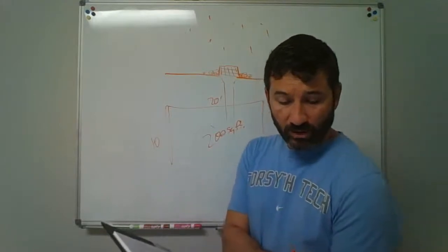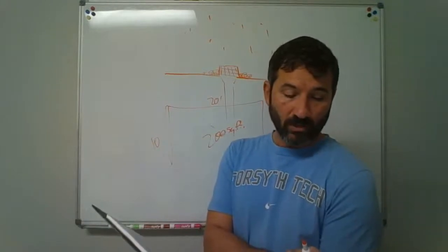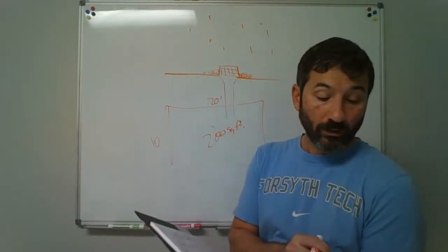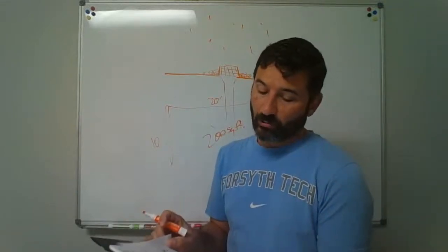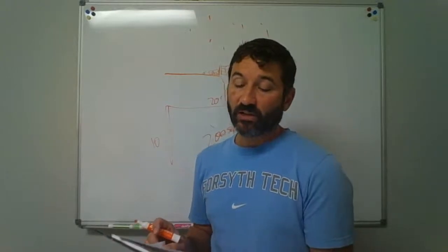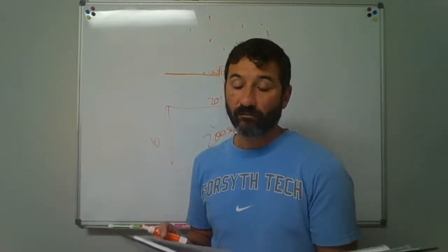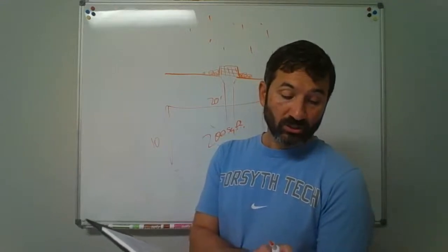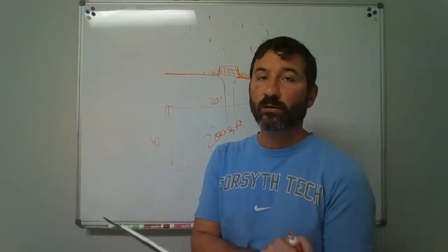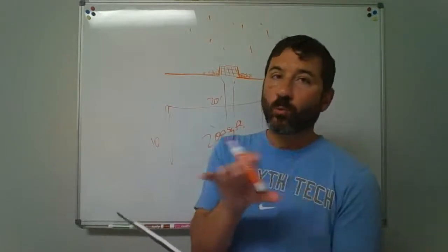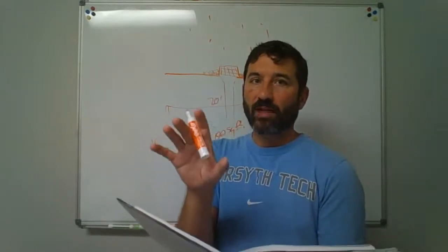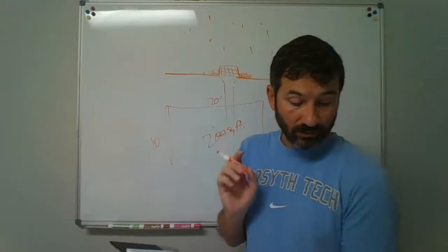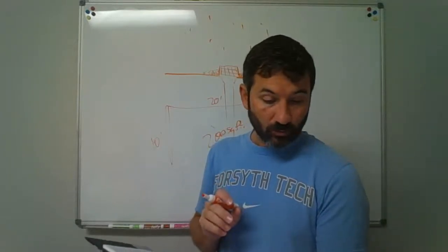Let's see. A 2-inch leader. If the area you're building in has a rainfall rate of, let's just figure on 4 inches. If we look back at that 100-year 1 hour rainfall chart, for us it was about 3.5, so let's just figure on 4. We'll go over to 4, and if we go down to the 2-inch leader, that's able to handle 720 square feet. So we find out where we're building, what the rainfall rate is for that area, and then how many square feet of roof we have. That's what size leader I need to handle all that. And you're doing the same thing with the bottom table as well.